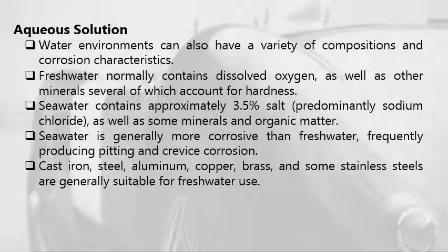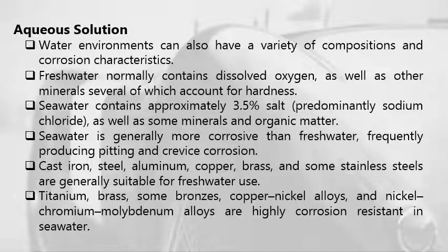Thus, cast iron, steel, aluminum, copper, brass, and some stainless steels are generally suitable for freshwater use. Titanium, brass, some bronze, copper-nickel alloys, and nickel-chromium-molybdenum alloys are highly corrosion resistant in seawater applications.